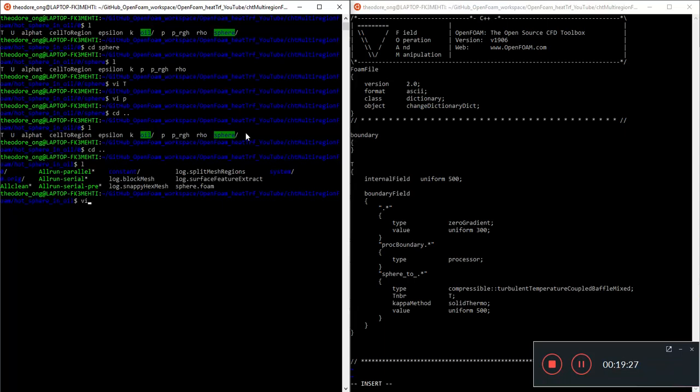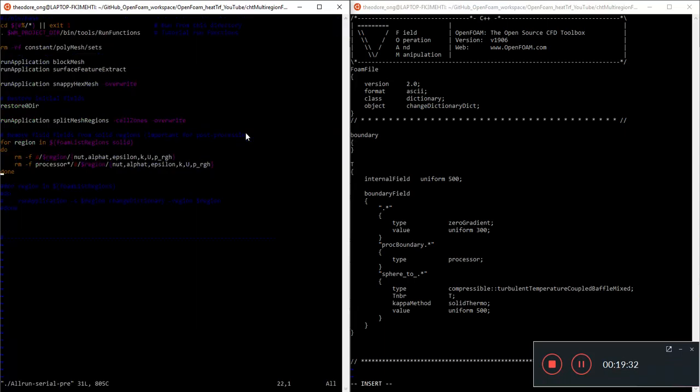So let's take a look at the Allrun serial pre. Okay, so what's going to be deleted is nut, alphat, epsilon, k, U, and PRGH. So pressure is still going to be there.